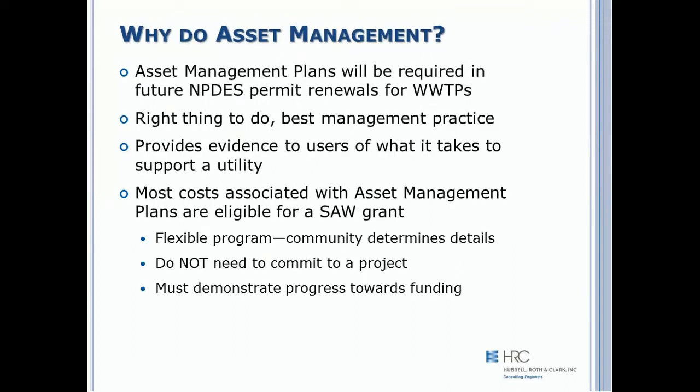Why do asset management? Asset management plans will be required in future NPDES permit renewals for wastewater treatment facilities. Right now, as permits are being renewed for facilities of 1 MGD or larger, these requirements are being put into their NPDES permits. It's also the right thing to do. It's a best management practice that will allow your utility to operate in a very effective and cost-efficient way.